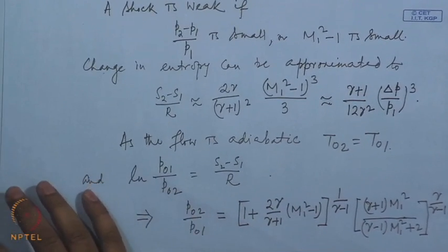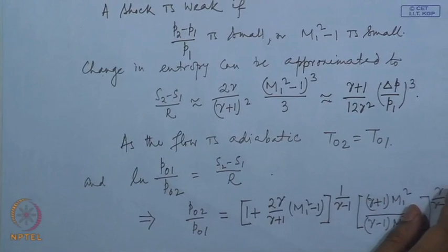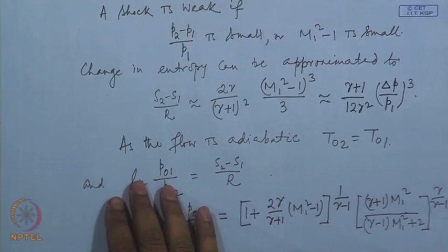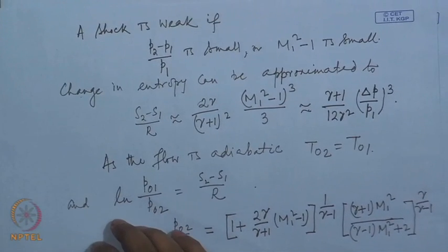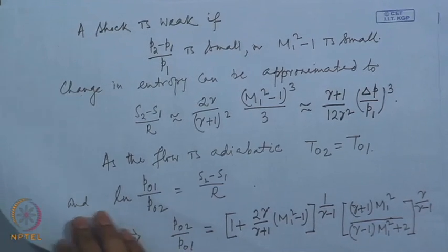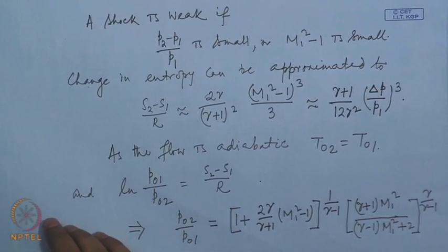Since we have considered one dimensional flow and the shock is standing across it, that is a normal shock, and in one dimensional flow that is the only possibility of a shock wave, a normal shock. And these normal shock relations that we have derived here assume that the shock is stationary and the fluid is flowing through it with a speed u1 upstream and u2 downstream.